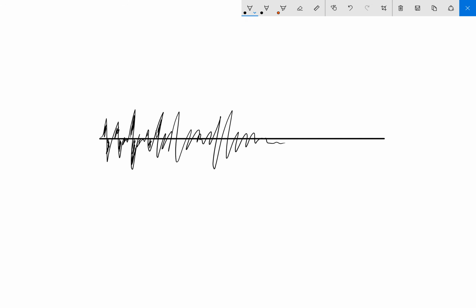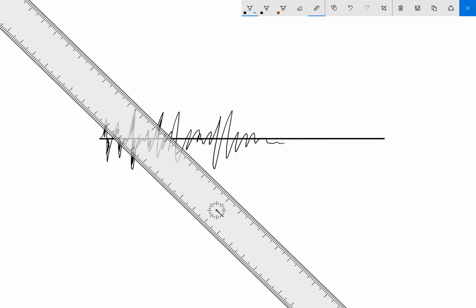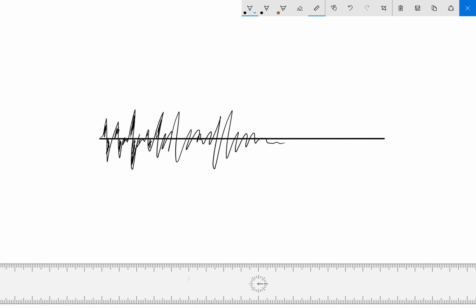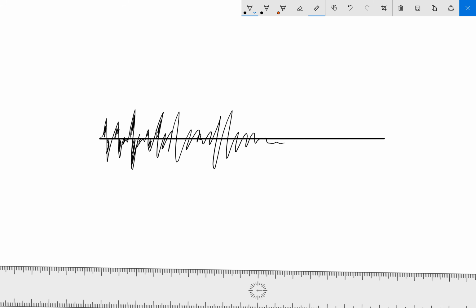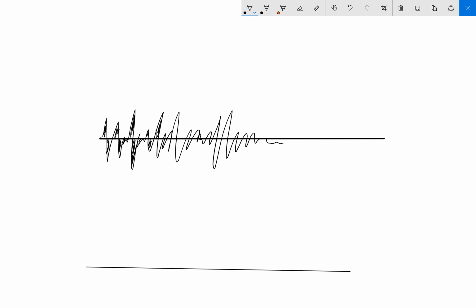And so what ends up happening is if I plot Arias intensity as a function of the time history, Arias intensity starts building with the time history and eventually tops out.